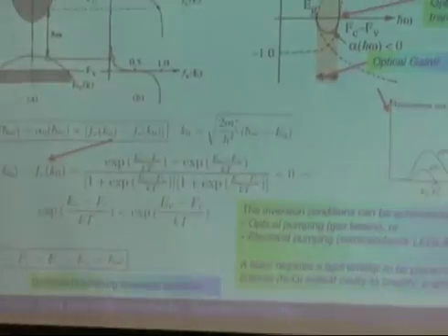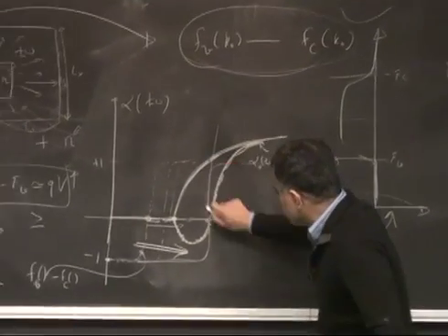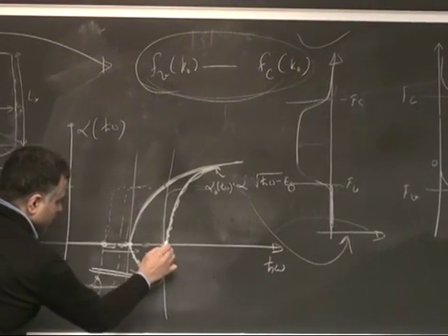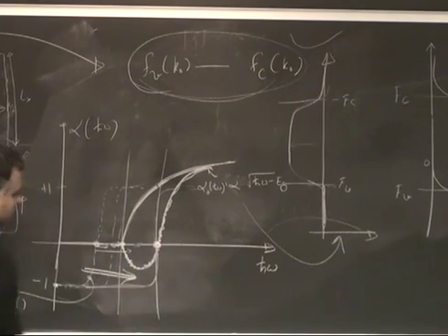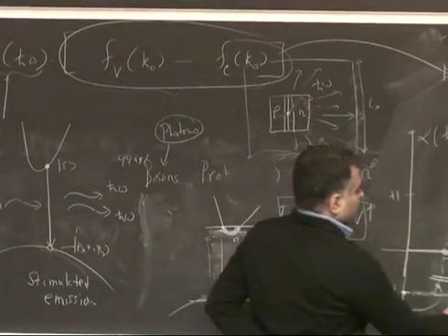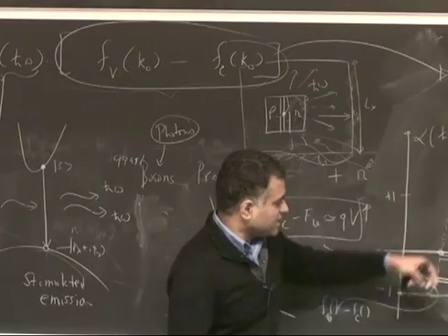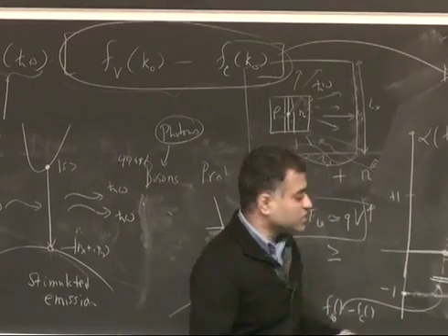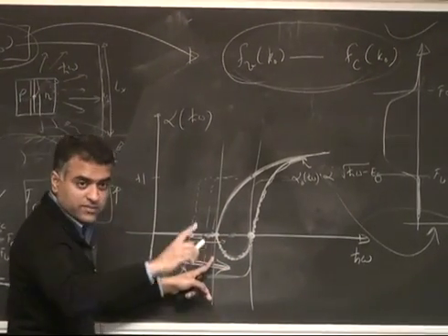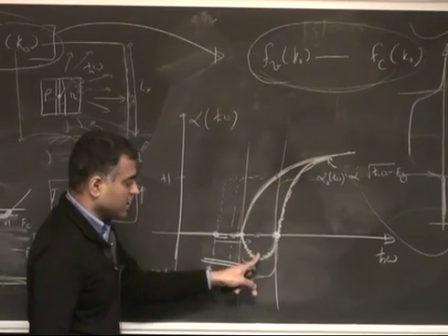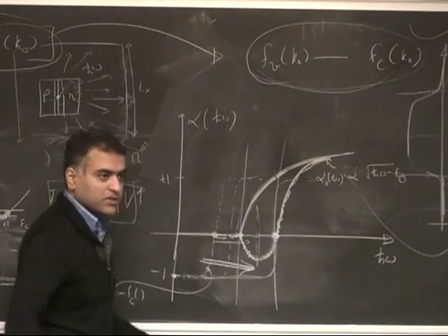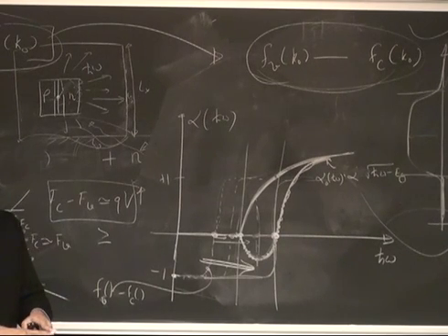So in this window, there's quite a bit of interesting things going on. You have a little slice of energies here, depending upon the threshold, I mean, the amount of current you are injecting and all that, right? So this point will be determined by how much voltage and how much current you are injecting. But remember when I said you have to design the mode such that there is one mode that falls, and which window should it fall in? It should fall in this window, because here your absorption coefficient is negative, and this is what is giving you gain, right? So in the laser cavity, you want the gain. Basically, the mode of the laser that you want to design should be somewhere right in the middle, so that you select that mode and you get the most gain out. Does that make sense?